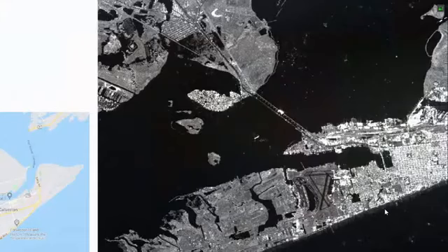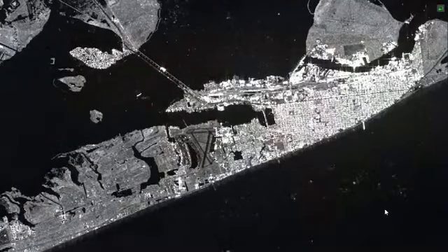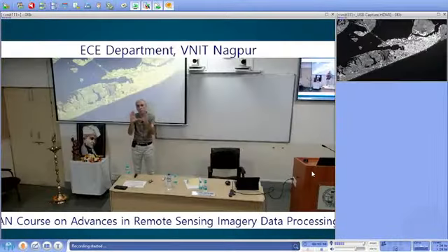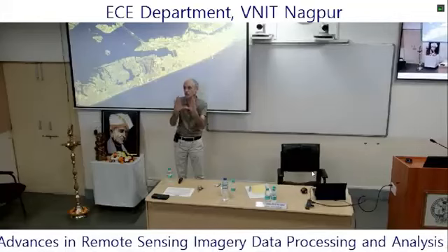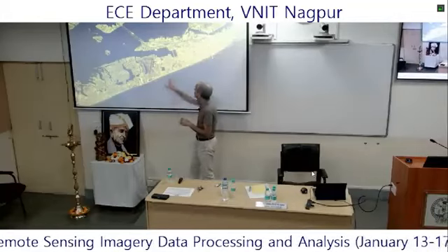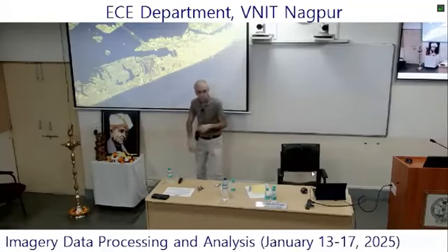But let's look at the urban area. Notice the very flat airport runway and the vegetation next to the airport runway. This is rougher, so it's brighter. Urban area. If you look at the direction, you can have an intuition of how these buildings are oriented. And you can see that they are more or less oriented as the direction of the satellite. So they cause strong backscatter.